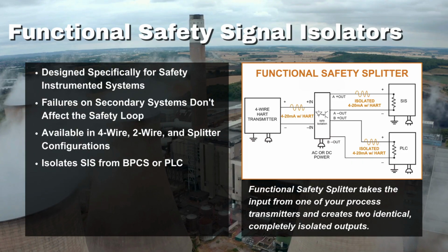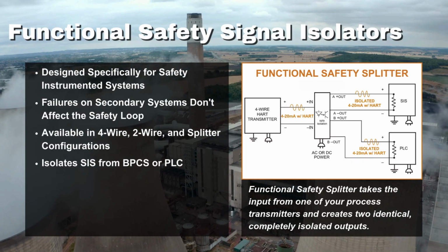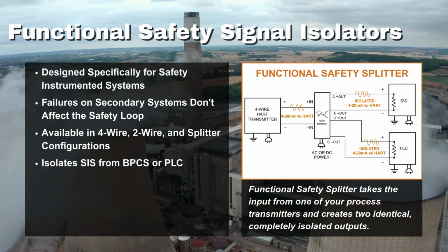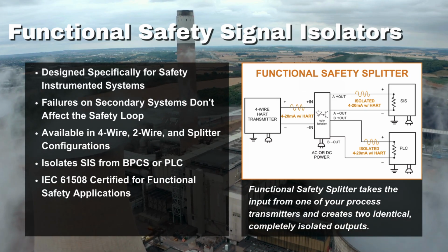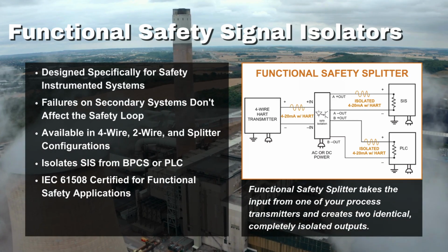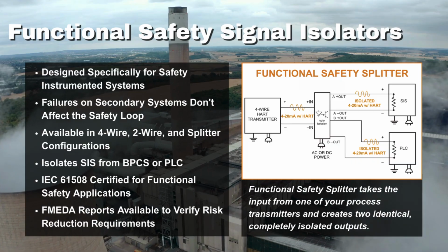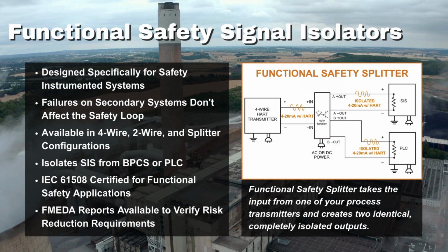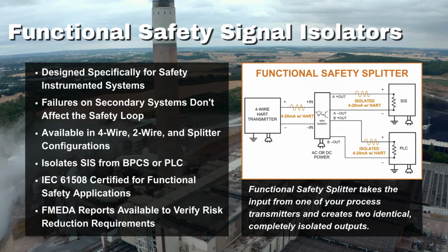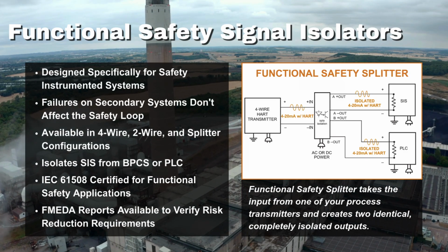When selecting a device for safety applications, a third-party approved isolator designed and built to IEC 61508 specifications is the best choice. Manufacturers can also provide FMEDA reports, failure mode effects, and diagnostic analysis, which supply the safety data needed to verify that risk reduction requirements are met.